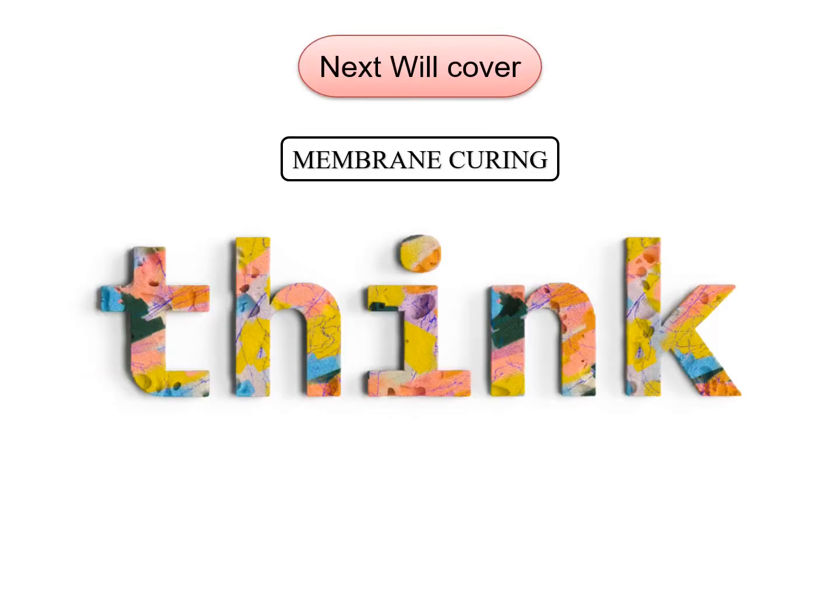So in the next module, we will be talking about membrane curing, where of course the temperature criteria won't be there like we consider in water curing, where you need to maintain the temperature of the water at 27 plus minus 2 degrees, whereas in membrane curing such requirements won't be there. But of course there are some other limitations of membrane curing which we will be discussing in detail in the next module.